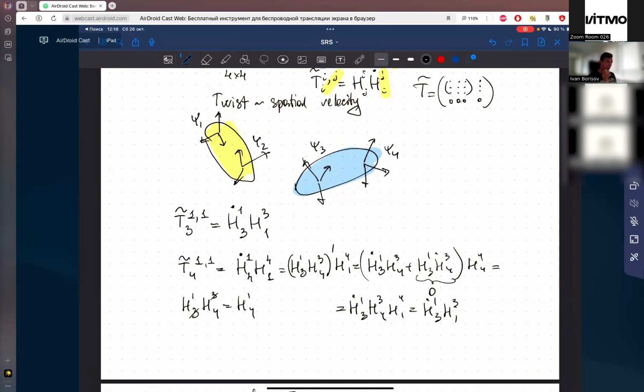The twist in the particular moment will be the same. So if you freeze time, for example, you do a simulation, you have integration steps, and if you freeze it for the integration step number n, the twist of each point that is connected to a rigid body will be the same.